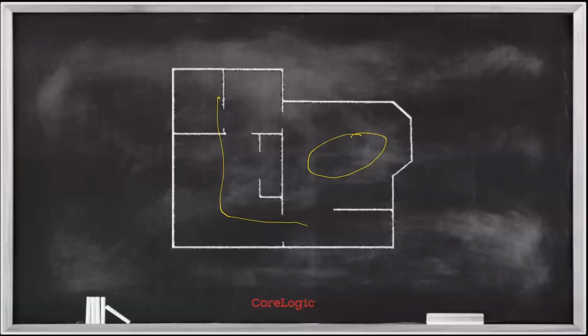Now, once I've established my drying chamber, at least my estimate of my drying chamber, and I've established the dehumidification that would be appropriate for that based on my class, et cetera, then the next step is to validate what a drying chamber is. And that is to obtain, and this is something I've stressed over a lot of different episodes here in Technically Speaking, because it's so, so important, a temperature and humidity value at one extreme of that chamber, one far end of that chamber, and then go to the opposite end of that chamber and take the same measurement. And what you're validating here is that the temperature and humidity are virtually identical, right?